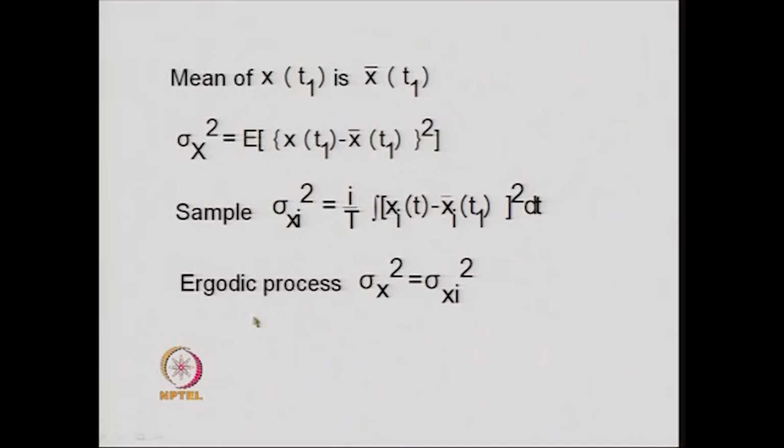Now, for our analysis generally we define a random process as a stationary process of order 2, or second order stationary process, if we find that the ensemble mean and the ensemble variance are independent of the time shift. And for engineering purposes, at least for structural engineering calculations, we satisfy ourselves with the second order stationarity.